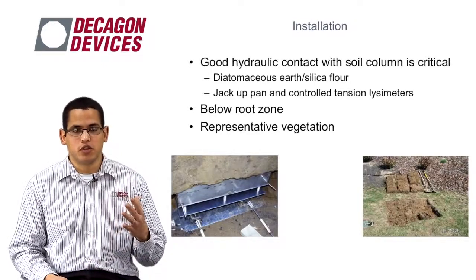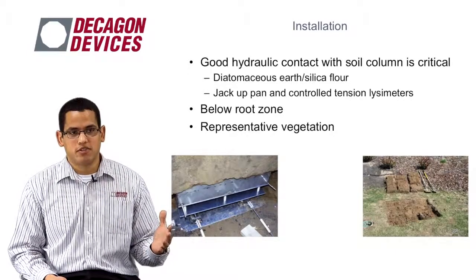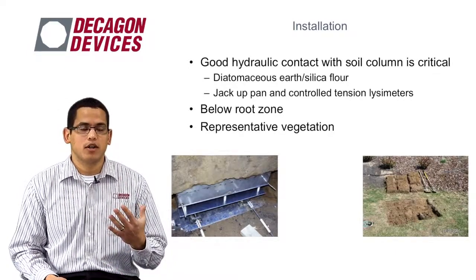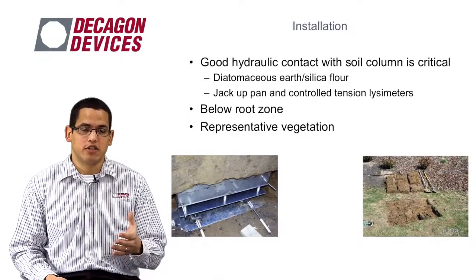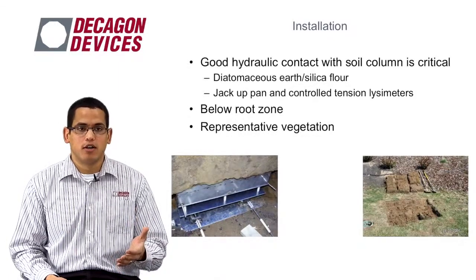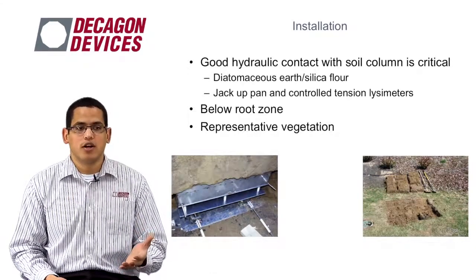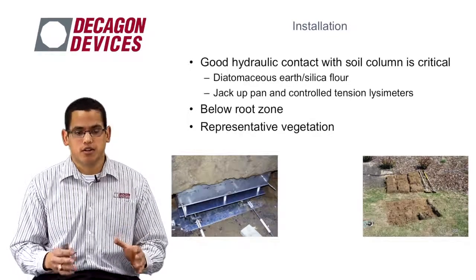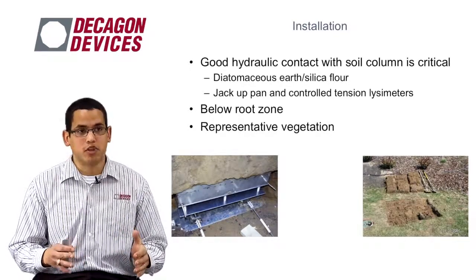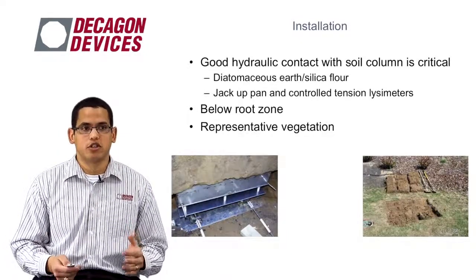It's also, if you're doing an installation with, say, a controlled static tension lysimeter, where you're actually having to dig out below the soil, it's important to try and maintain the vegetation above it for faster recovery, and that way, with your measurement, you start getting more representative values earlier on within your study.